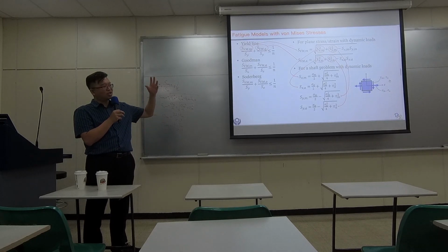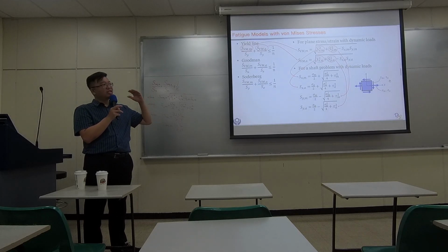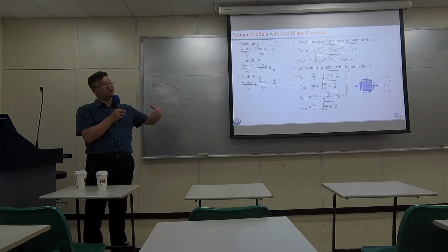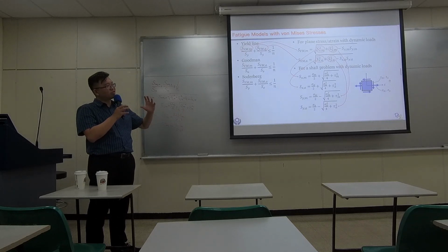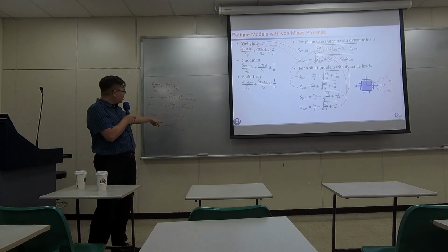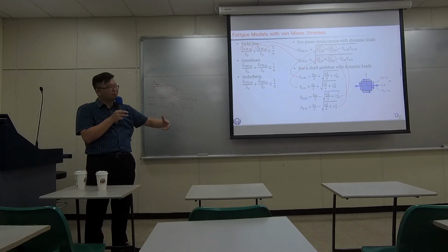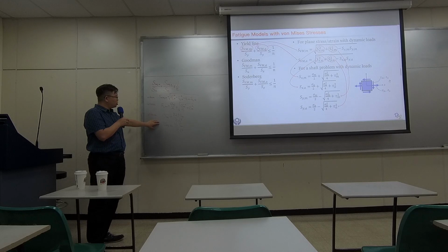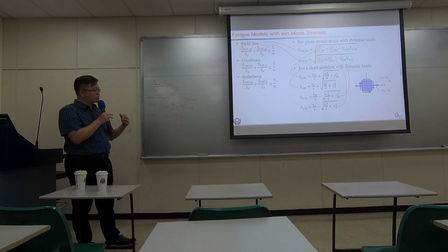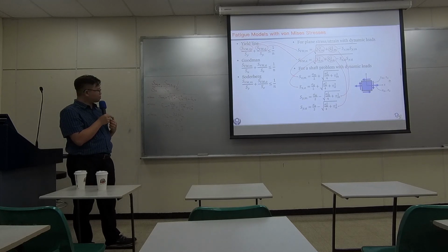Then the load applied to the shaft is always changing, varies with time. So if the stress varies with time, or if the moment and torque vary with time, here's where you want to take a look and see if that load condition is going to cause a fatigue problem.